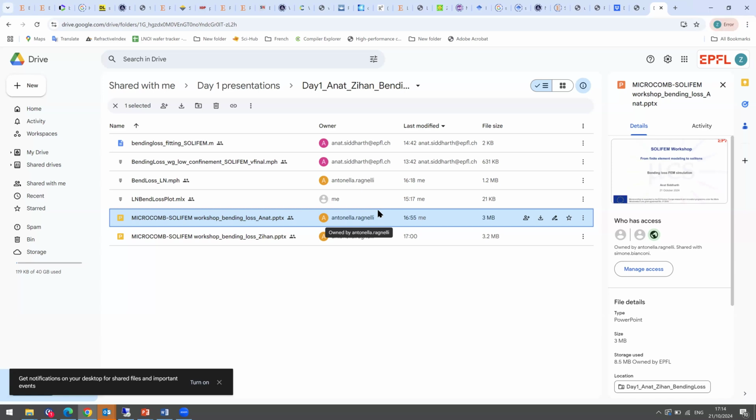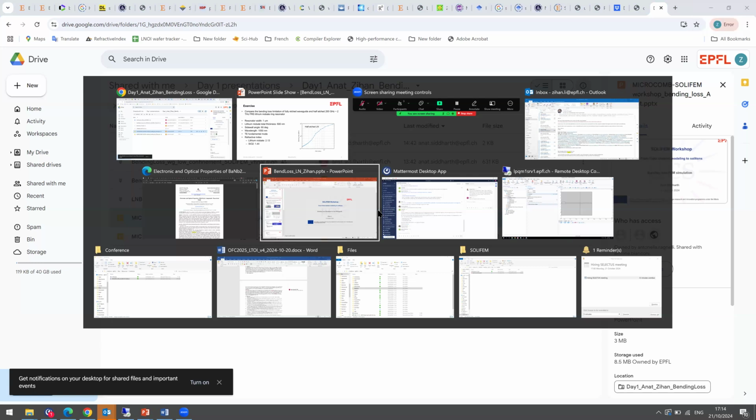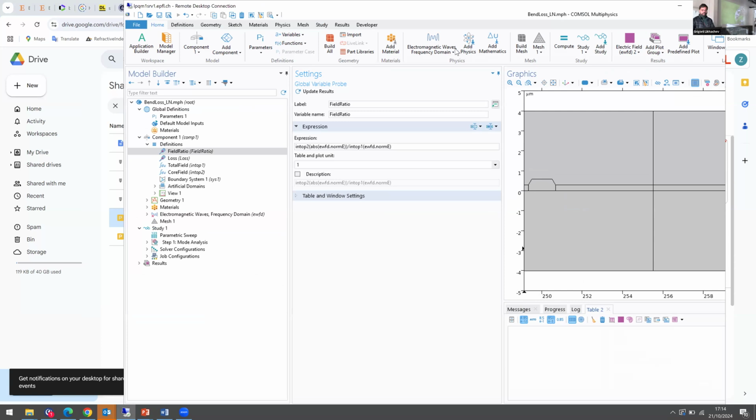If you can open the previous model, remove the multiplication R SIN 1 meter, just remove that and only put 1.54 and run it. Do you see now the largest refractive index of each radius, and that is confined in the waveguide? Okay. Now can you go to the derived table, to the results?